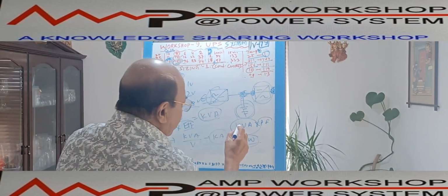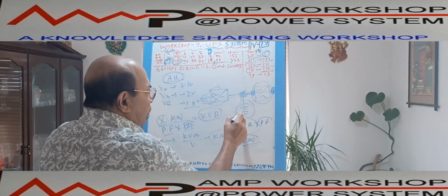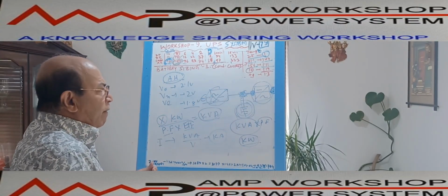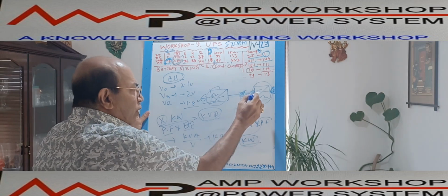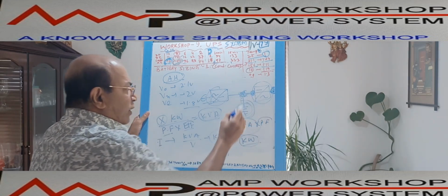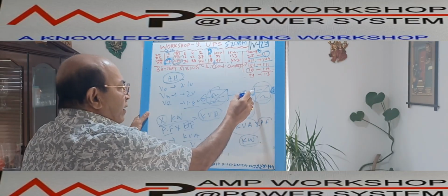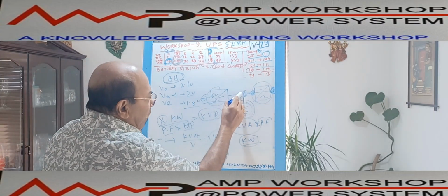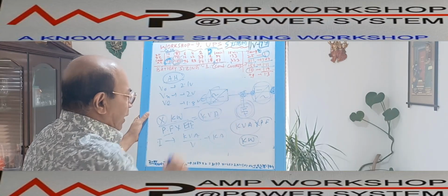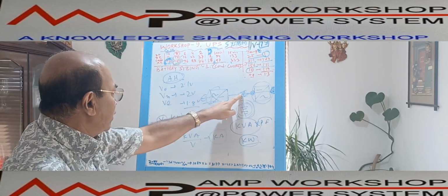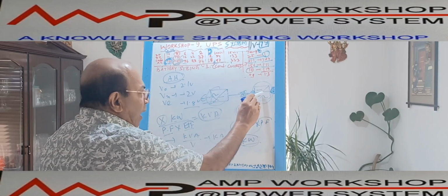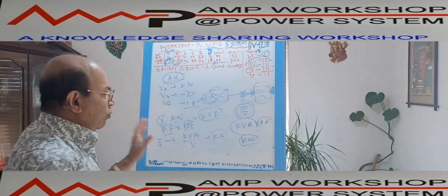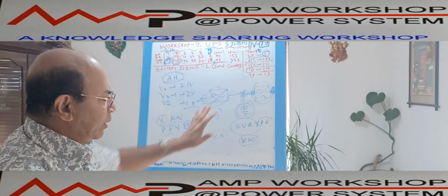So when we discuss the inverter input, the DC current or battery current, we need to know the output of the inverter, and then the inverter efficiency and inverter power factor. By getting these parameters, I can get the input kVA. Once we know the input kVA, then we need to know the battery voltage, the DC voltage over here. Once I know the DC voltage, I can calculate how much current the battery needs to deliver for the X kilowatt of power. In this way, I can calculate the battery current at this point.